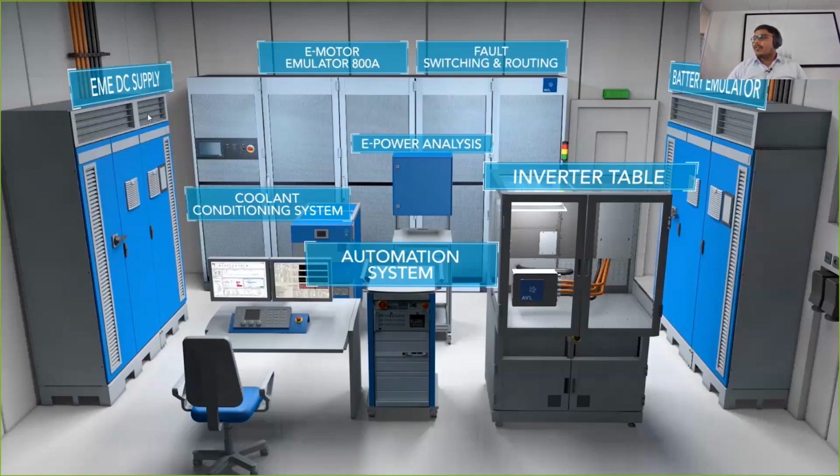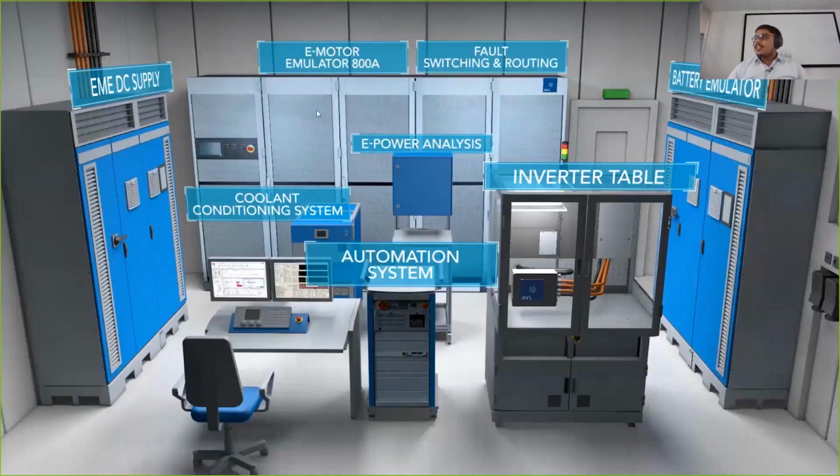And then in the background here, we see the E-Motor Emulator, the Electric Motor Emulator. From now on, I will use the word EME as a short form for the Electric Motor Emulator. This EME consists of a control cabinet and high-performance power architecture, capable of handling currents of more than 1,600 ampere, since it's modular; in this figure, it's only a representation of one configuration matrix.